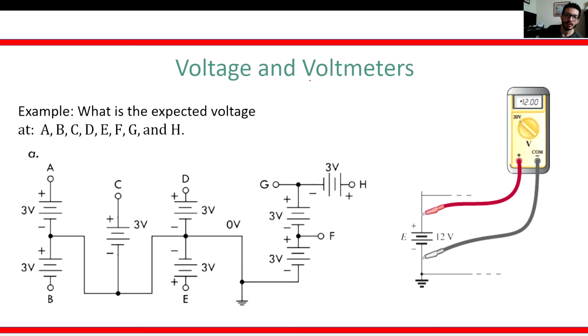Now, as we saw using Tinkercad, you can use voltmeters, and the concept for measuring voltage with a voltmeter is that you simply place your black and red probes at the points on the circuit where you want to measure your voltage, and you don't have to break your circuit. You can just place the probes at two different points. If the voltage is the same, then you're measuring the same potential. If it's a different voltage, then you're measuring a difference. In other words,